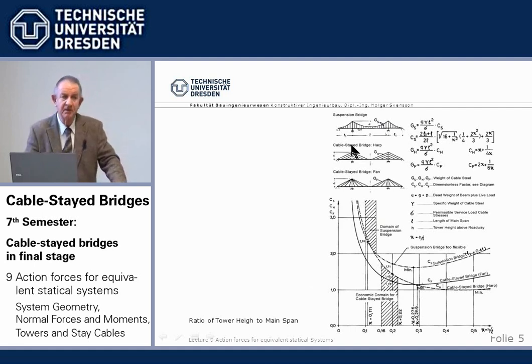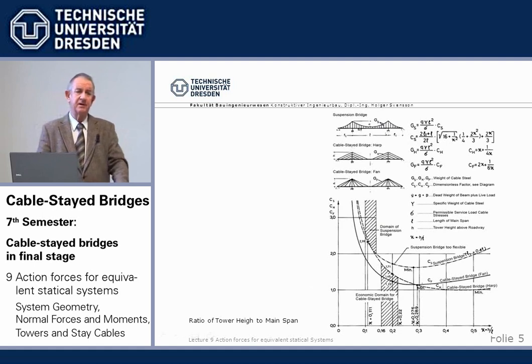Again, as I keep repeating, we want to achieve the minimum cost. In real life, we're always in competition, and the bridge which costs the minimum will win and will be built. So what is, in this case, governing the tower height is the amount of cable steel required.